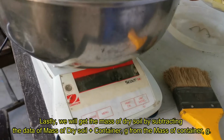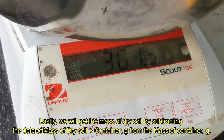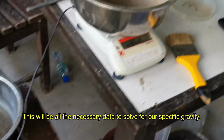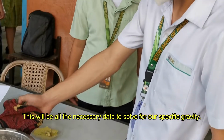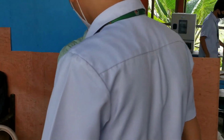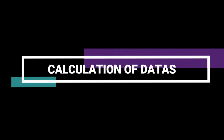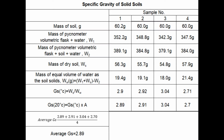Lastly, we will get the mass of the dry soil by subtracting the mass of the container in grams from the mass of dry soil plus container, also in grams. Now, this will be all the necessary data to solve for our specific gravity. And next, we have here the table for the calculation of the specific gravity of the solid soils.